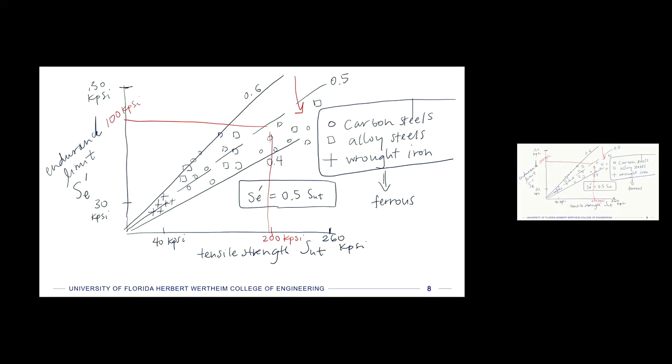Okay, so this is good. This gives us a starting point. And if this gives us a starting point, and we had another data point we could point to, we could draw up an SN curve without having all the experimental data, and at least get some estimate of the slopes of it without having to have that particular material tested. So I'm going to draw another SN curve here.